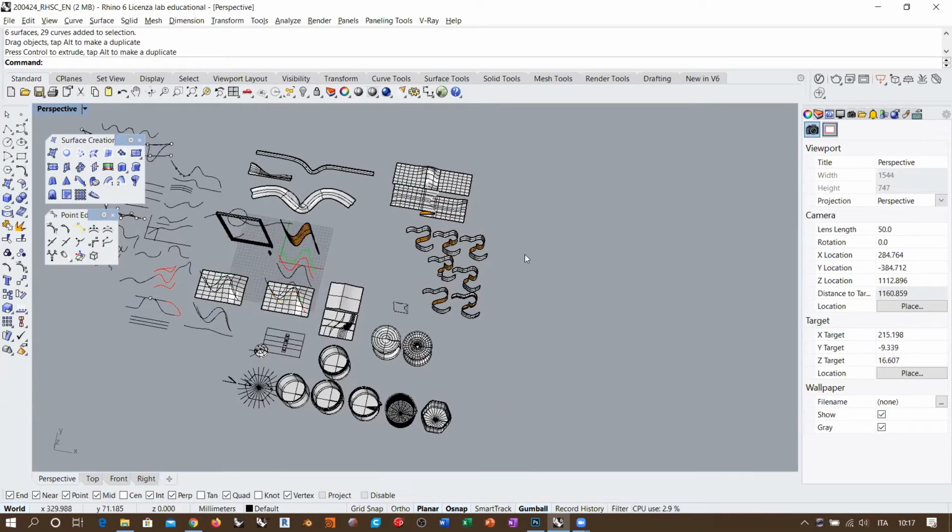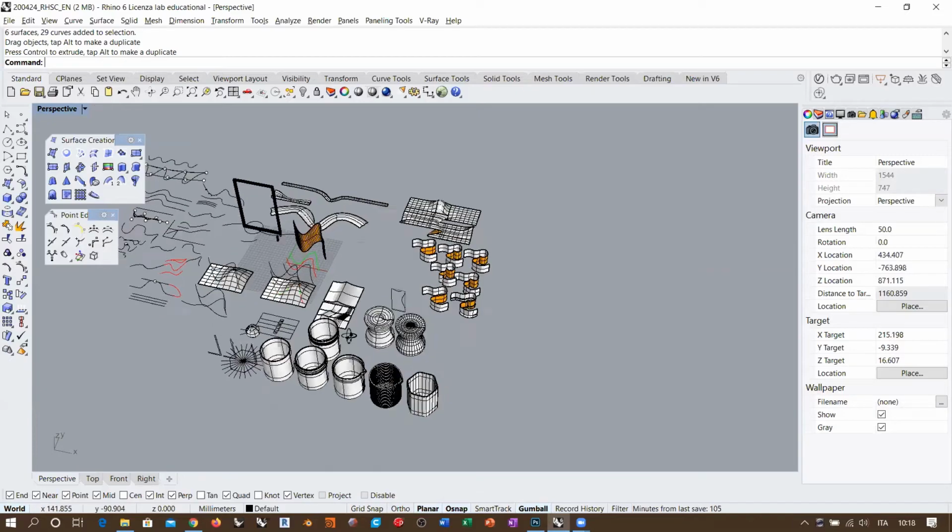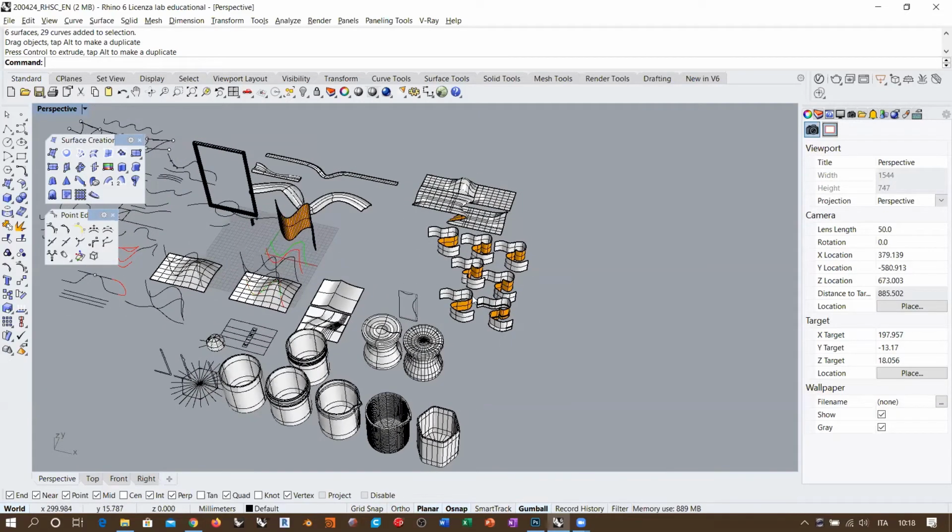Okay, as you can see, also the revolve surface, which is a very basic command, when you analyze it from the topological point of view, has some tricks that you must consider in order to get to the right result in less time with less effort. Now let's go to the problematic surfaces. Which are the surfaces that I don't recommend using unless you are at the end of the modeling workflow, so you basically don't need to do any other operation on that surface, or that kind of surface is absolutely the only choice you have for solving a very precise modeling step.